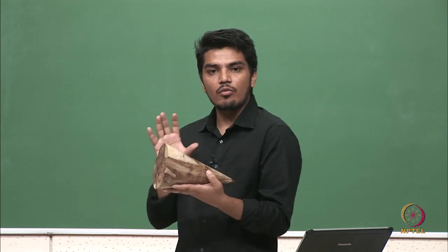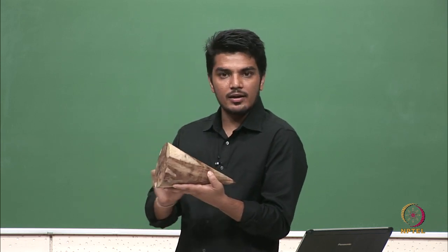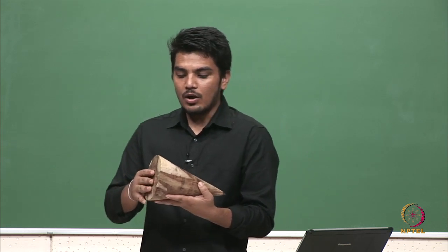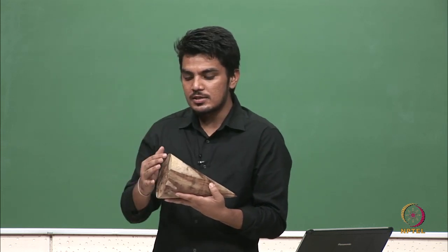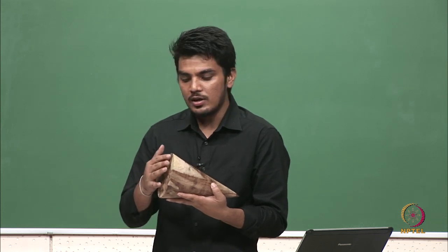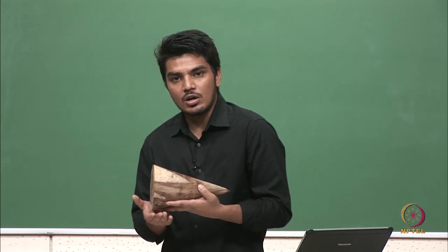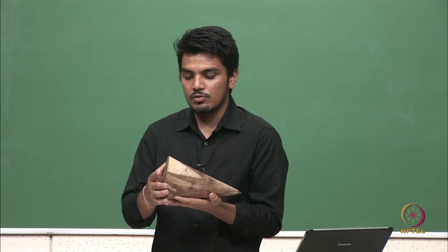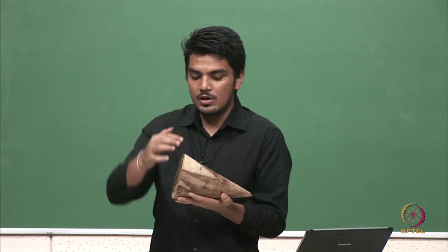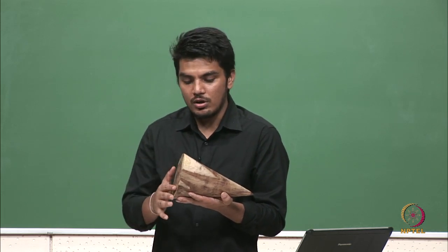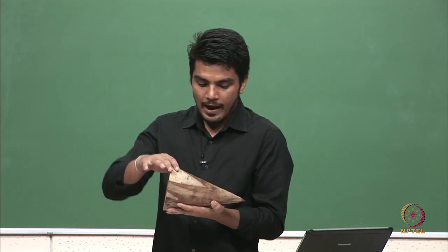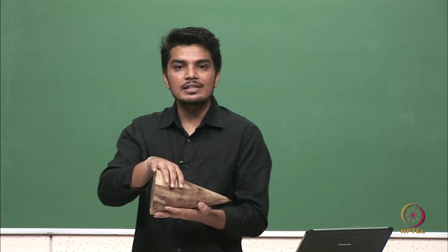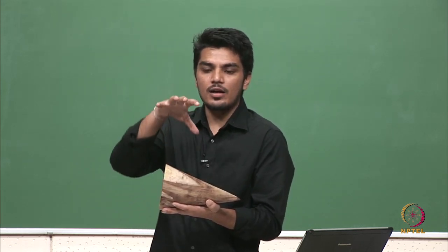Now, on seeing from front, we will get the same triangle as obtained in the first orientation, but on seeing from top, since this base of the cone is not perpendicular to the horizontal plane, we will get an ellipse. Again we can visualize it. On seeing from top, this base of the cone can be seen as an ellipse and its surface can be seen as a triangle. So, we will start with front view followed by the top view.